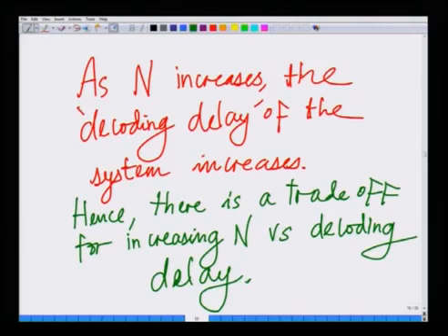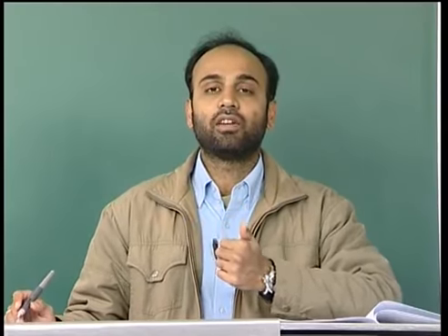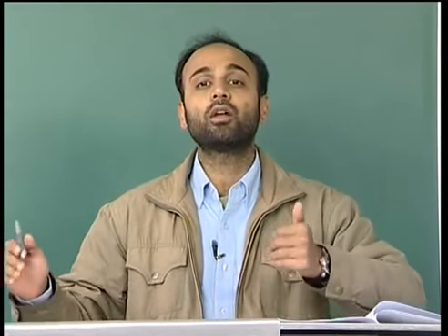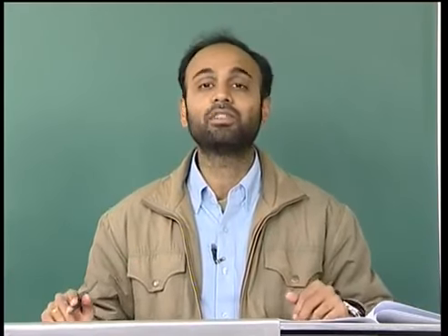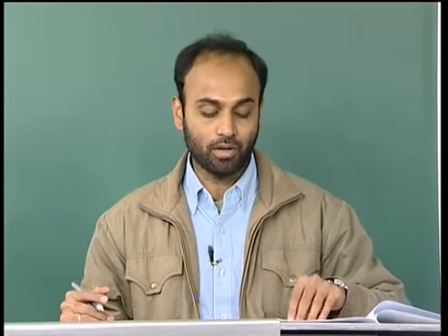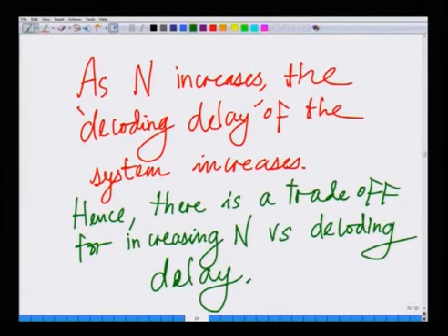If you increase the number of subcarriers to a very large number, you will have progressively more and more delay in decoding all these OFDM symbols, which might not be suitable in some applications. Let's say you have an audio or video application which requires fast data to be decoded. For instance, if you are watching a movie, you have streaming video, and you have to have a frame that is decoded every so often. You cannot have a large delay for decoding these symbols. Since that is so, the decoding delay is also a very important parameter in systems, especially 4G wireless systems. All right.